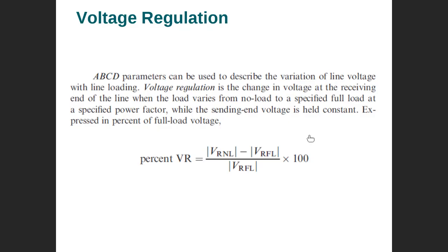Okay, so this is voltage regulation. You want the voltage regulation to be within short limits, maybe plus or minus 5%. But if it is huge, then you need to take some measures and correct things there. As an engineer, you need to correct. That's what you study, the system. This is in the planning stage: when they do planning, you need to study the voltage regulation.